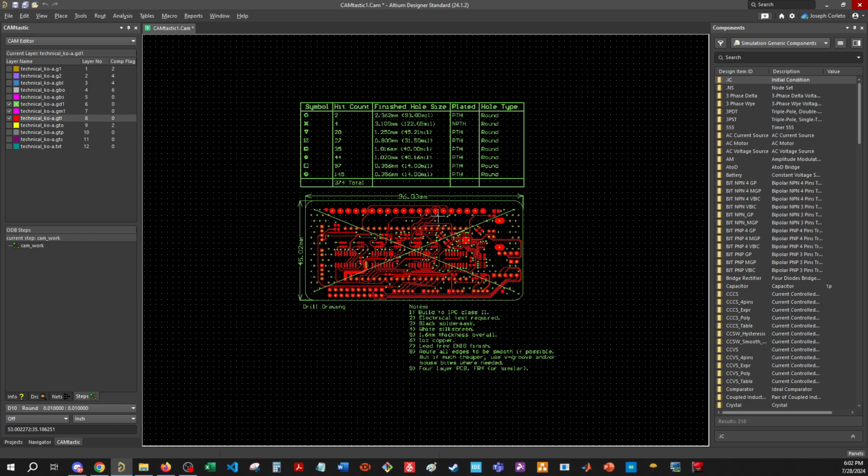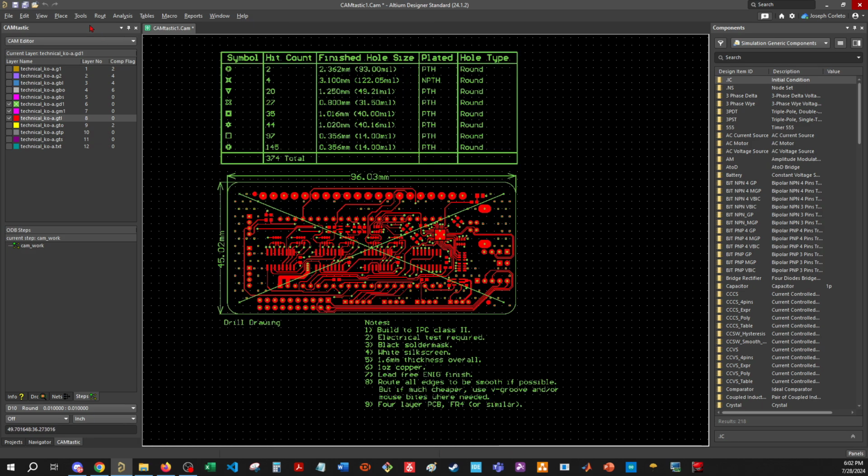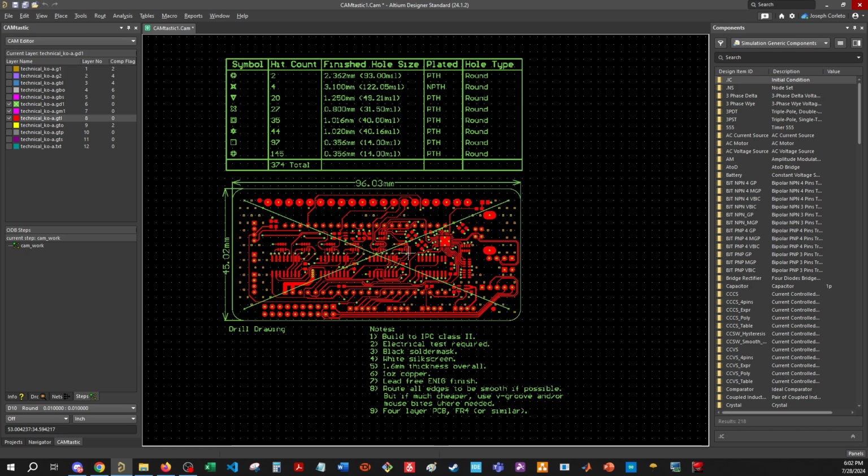Based on certain primitives and certain relationships between the layers, you're able to actually go ahead and align. And you could do other things too, like draw on the Gerber file. I'm not going to show you that because really I've only used this Camtastic tool for alignment purposes, not like drawing actual primitives. You can do it, but I've had no reason to.